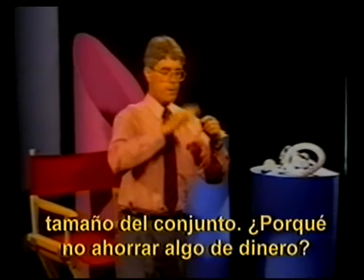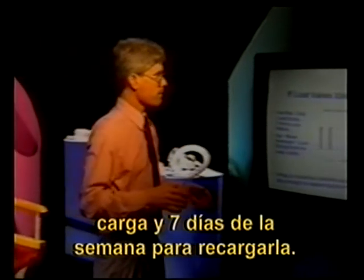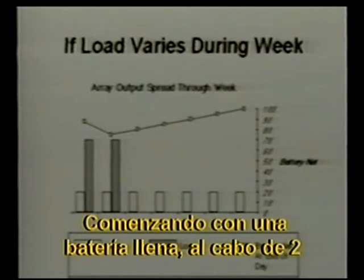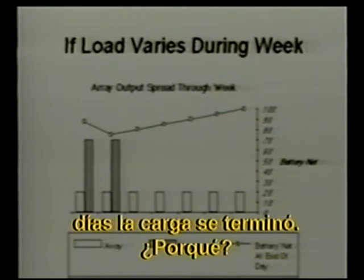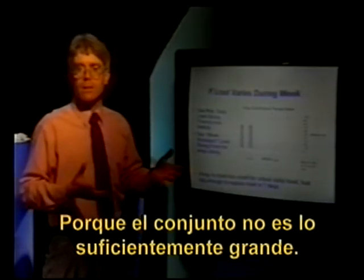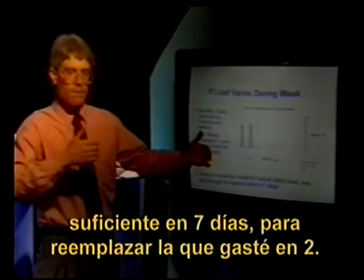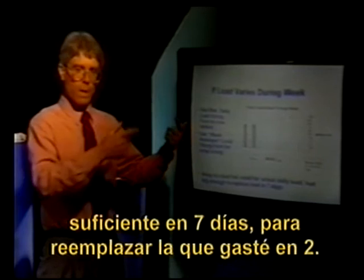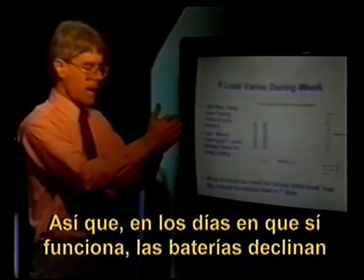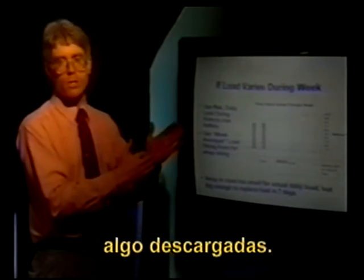So let's take a look at what the profile might be if you only had 2 days of load and 7 days in a week to recharge it. Graphically, we can show the load operating for 2 days. Starting from a full battery, by the end of 2 days, we're down in terms of battery state of charge. Why? Because the array isn't big enough. The array is sized to give enough energy in 7 days to replace what I've used up in 2. So on the actual days of operation, my batteries get dipped into a little bit, and they're left at the end of the weekend slightly discharged.